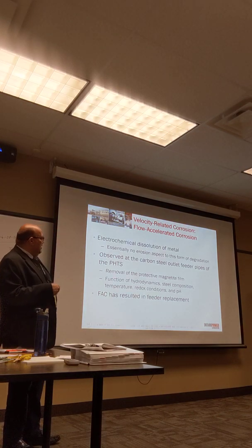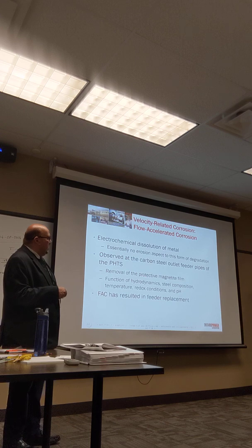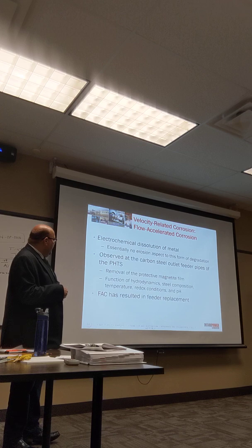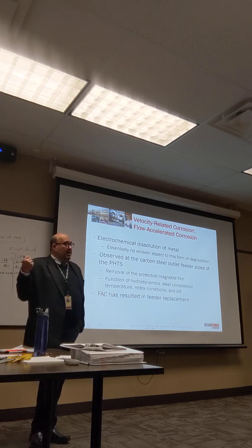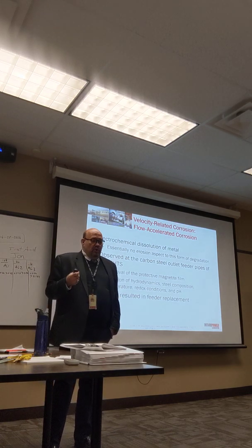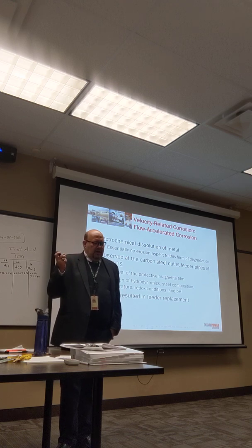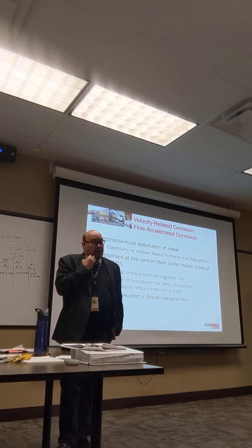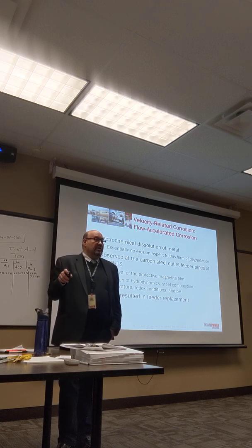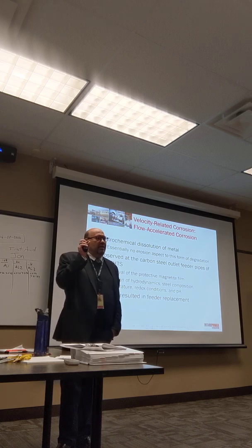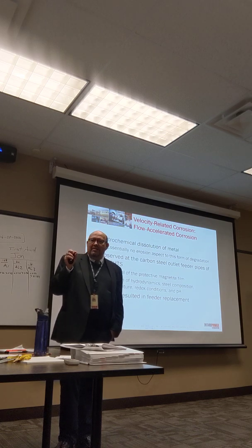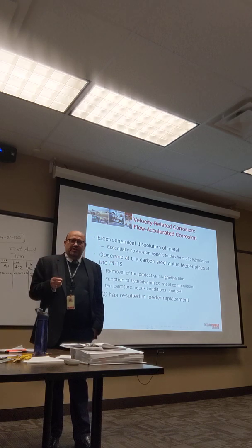So again here, and that's what Anil was talking about, the removal of the protective magnetite film. This is in the feeder pipes, and FAC has resulted in feeder replacement. I remember about 15 years ago, I was working on a feeder at Bruce Power that was changed maybe 12 years ago. I did the stress analysis for it, and we had something like 100 thou left, or 99 thou left. Later on, they replaced it a few years later.